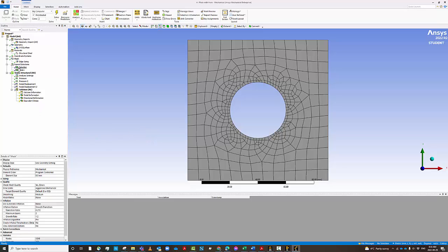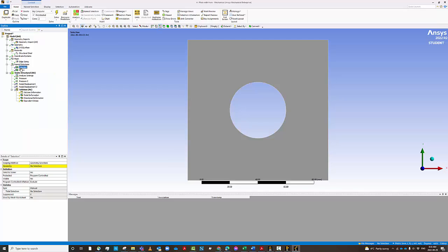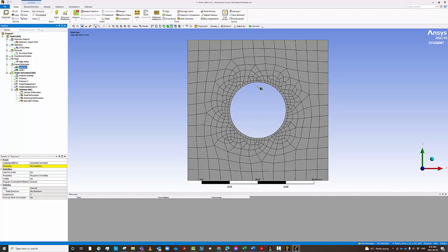The second problem now is that these points are no longer valid, because when we selected the nodes, we selected from the old mesh, right? So now these are not going to be valid. So if you go to this node here, selection, we have to insert our new node. So we go here, it's going to show the mesh, and I'm going to select a new node for it and apply. So now it is good. I go to node number 2, and I'm going to select this node again and apply, which I didn't do before. So these are the new nodes, and you see here these are also changing. Now the nodal constraints are on the new nodes, because when you change the mesh, things have changed.